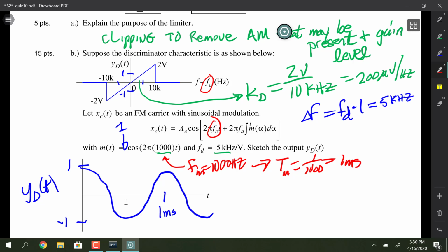remember you worked with the radio boards, and those were RFICs, but they had an external discriminator tank circuit for the quadrature detector, the FM detector that was in there. And that gave some discriminator gain constant, but I don't remember what that was. I think you read in the data sheet for the chip, and it gives you approximate values for KD, probably with a certain type of inductor that you'd put on there external to the circuit.